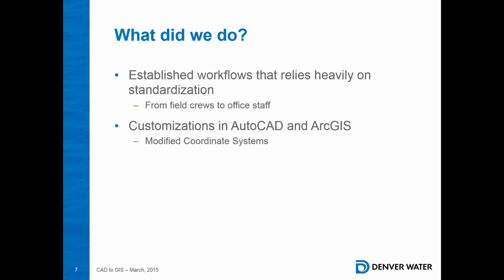Yeah, this is one for those of you who've been in my CAD to GIS class or out at any of the GIS in the Rockies, or anytime I talk about coordinate systems, I talk about grid to ground conversion and all the different ways that it can be accomplished. And in CAD, there are some good ways and some bad ways. And I know that historically, because of the limitations of CAD, a lot of the Department of Transportations are a bit limited in what they can ask CAD people to do. So typically they're looking at things like a direct scaling from 0, 0, and things go shooting 800 feet off into the wrong direction. And I can see out in the ether there, many of you are nodding right now.